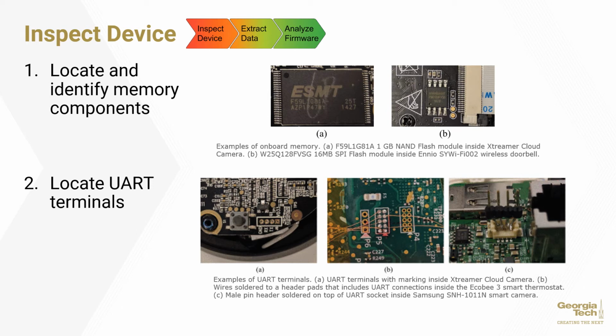Taking apart existing IoT devices is possible in most cases since they're just encompassed in metal or plastic and they're just held together by screws and glue. So once you've opened up the device, the first step is to locate and identify the memory components. A number of IoT devices contain memory components outside the microcontroller since they need extra memory. These components are where you can find sensitive data such as the user application, boot code, bootloader, a wireless stack, or any other essential components of the system.